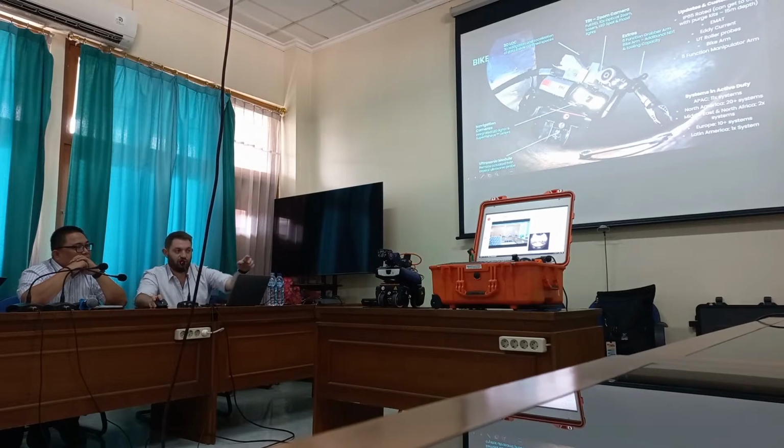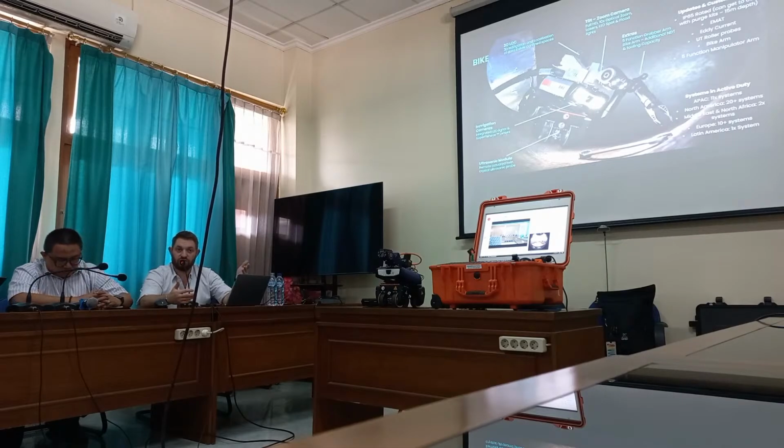So this is a camera that goes up and down and is in full HD and has integrated lights in it, because we need to be able to adjust and control our lighting when we're looking at an area. We've got forward and rear-facing fisheye cameras, so they can see about 220 degrees. So we can see the front wheels in the robot, the side, on both the front and the back of the robot. We've got it on the back because when we're driving through areas, we need to be able to see what our tether is doing. Have we got it caught on some internal piping? Is it caught on a vortex breaker, etc.?